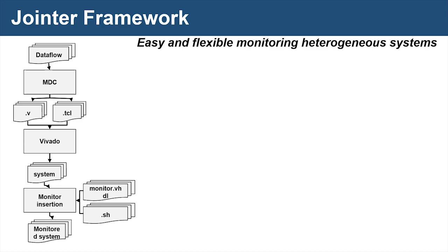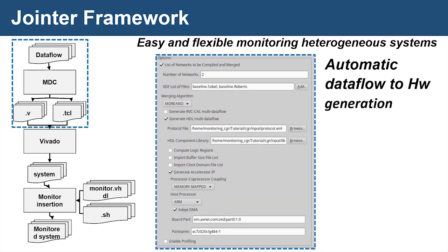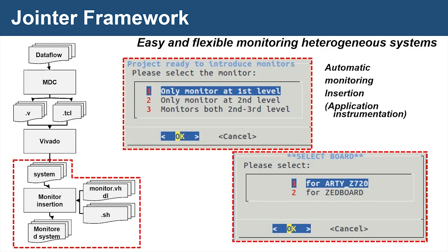It is basically an integrated design flow for the development of customized monitored complex heterogeneous architectures, composed of programmable processors and dedicated accelerators on FPGA. The design flow, starting from dataflow specifications, generates heterogeneous dataflow-based coarse-grained virtual reconfigurable systems. In these heterogeneous systems, the monitors are automatically inserted at different levels in a composable way.